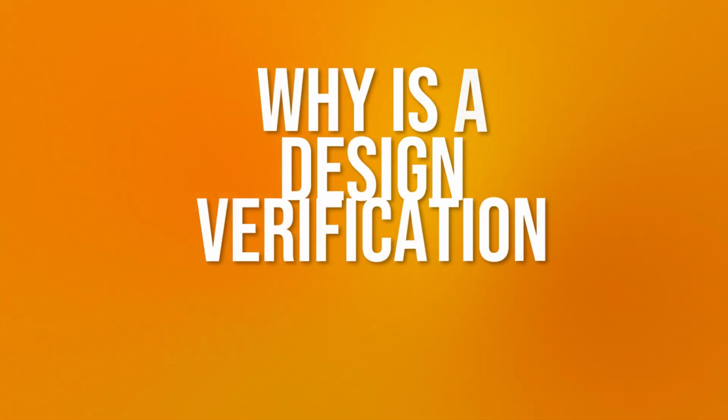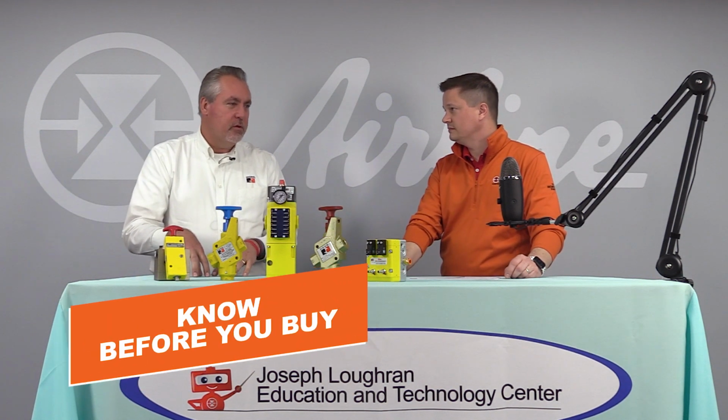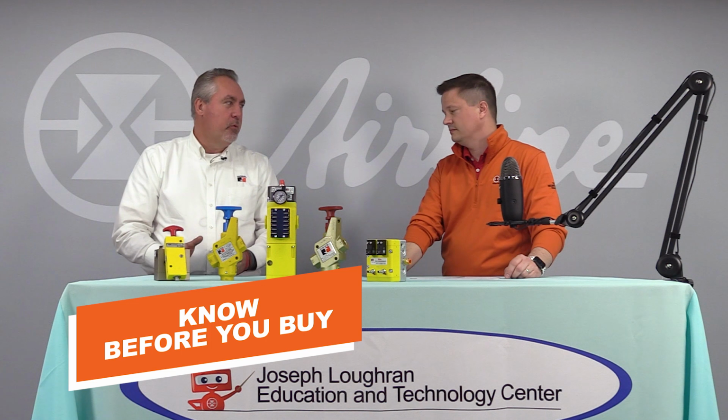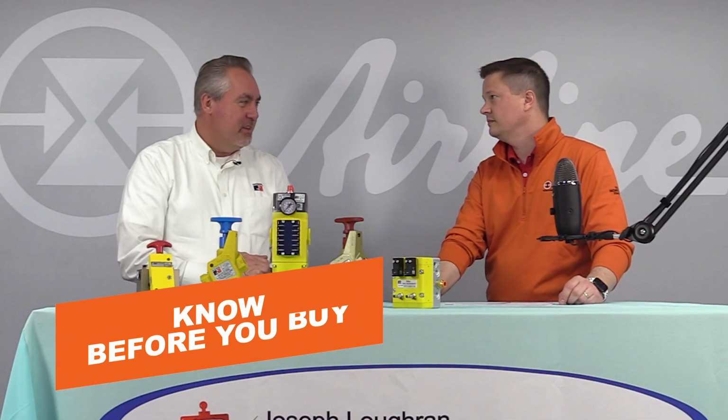So why is a design verification best practice? Well, what a lot of people have done is adopt standards like ISO 13849 or IEC 62061 out of Europe, or follow ANSI B11.19 or B11.26, which basically gives you the ability to calculate what performance level or SIL level you're achieving before you ever buy the first component. It keeps you from wasting money, really.